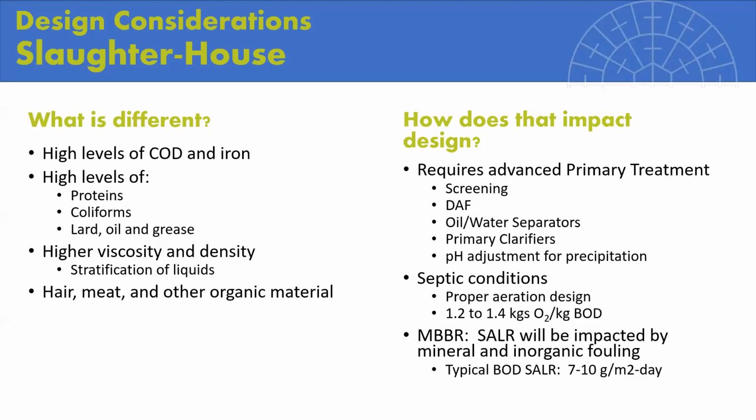Historically, MBBRs that used coarse bubble aeration generated a lot of pin floc. So that's why in a lot of cases you find MBBR and DAF systems work very well together. Based on our experience, when we combine MBBR with fine bubble aeration, we see less pin floc formation and much better settleability in clarifiers. So in most cases, we're going to design using a lamella system. Kelsey, next slide.